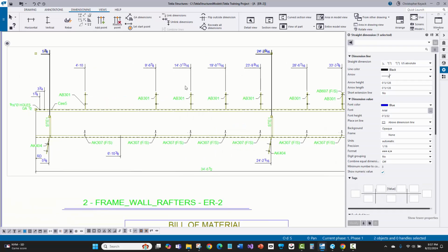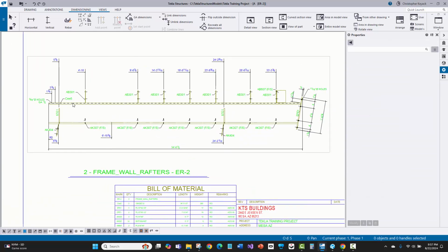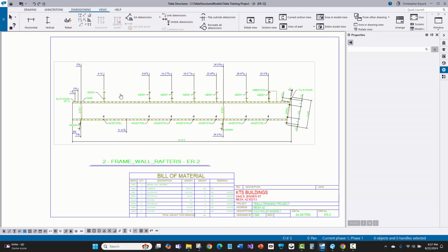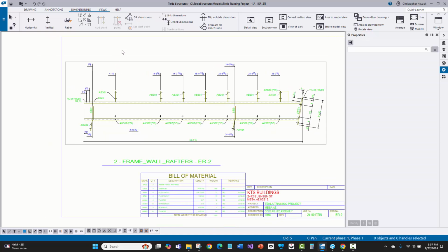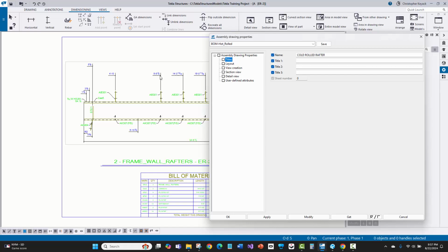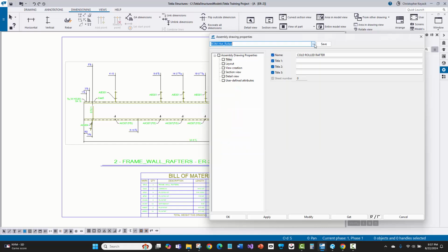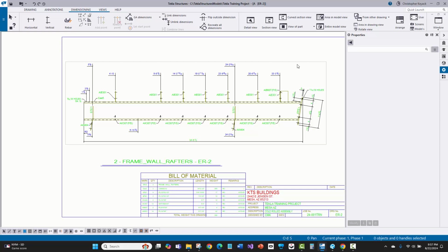And I've got my dimensions to my stiffeners. So this is looking pretty good. I've got just about everything there. I probably need to cut a section just like I did on the other column and rigid frame rafter drawings. But this is looking pretty good. And the main thing I wanted to convey in this part of the video is that sometimes the cold rolled settings or hot rolled integrated is not going to work. You're going to get kind of overkill in the dimensioning using the conventional steel dimensioning settings. So I just switched that to this hot rolled type, and it's going to use more settings that are similar to a rigid frame column or rafter and be a little bit more minimal in the dimensions, and you just have to tweak a few things like you see here.